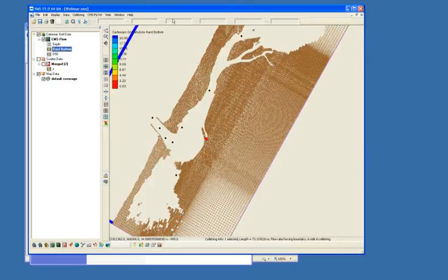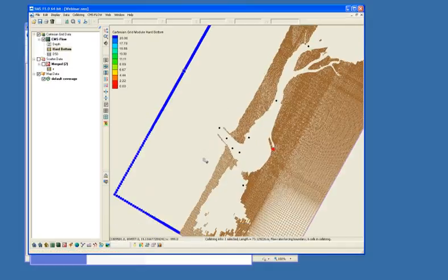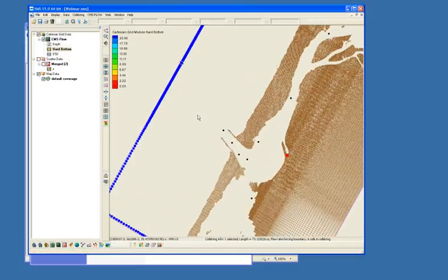So I was mentioning hard bottom earlier. How do you affect the values for this? If you look down here at the bottom, you're seeing a negative 999 everywhere, and basically that's the default value for hard bottom. It essentially tells CMS that for every cell that has a negative 999 as a flag, CMS can erode as much as it needs to get the answers.